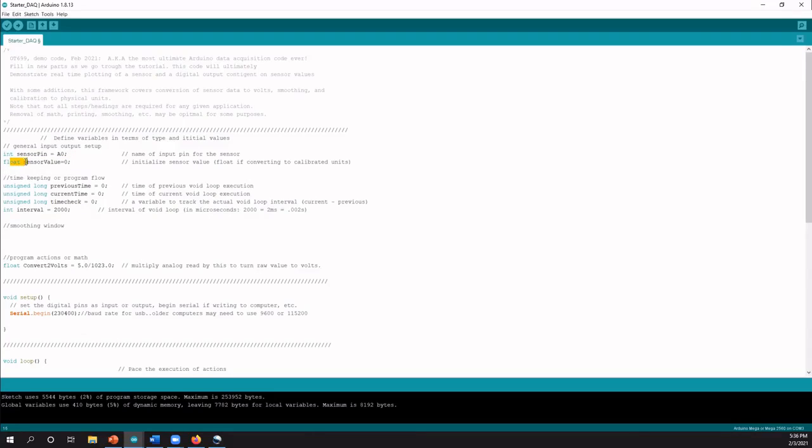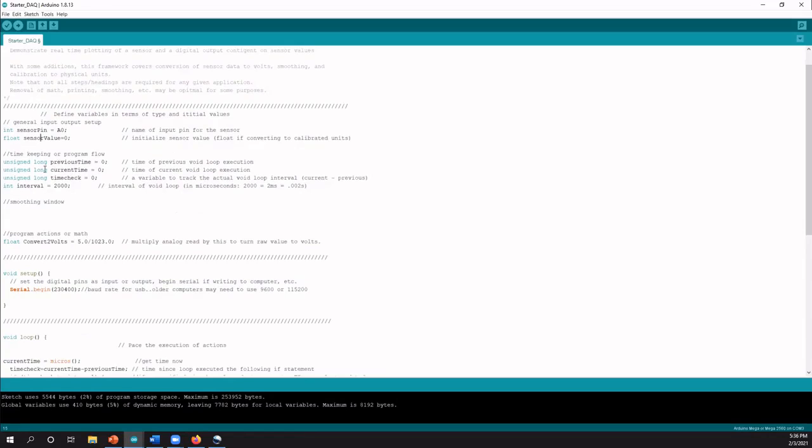I'm using float here because in the future, I plan on turning the sensor value into a voltage between 0 and 5. If I was happy with just some number between 0 and 1023, I would probably also call this int, for integer. You only really need to know float and integer, with the possible exception of unsigned long. All the rest of the possible formats you don't really need to know about. Unsigned long, however, is for the next block.